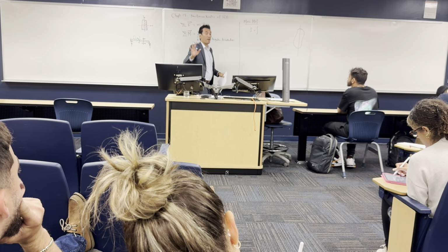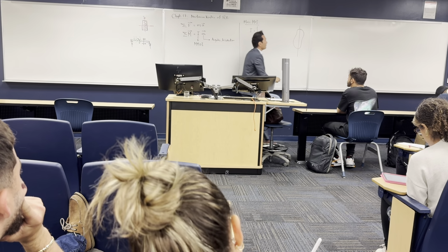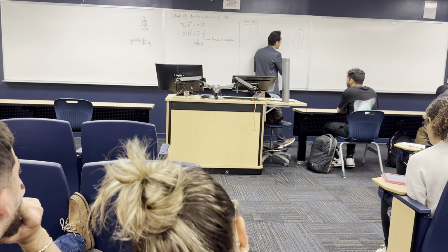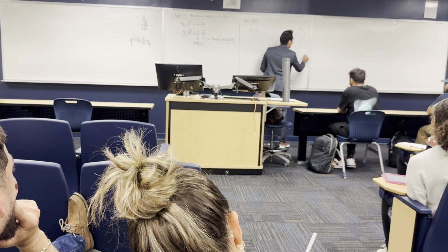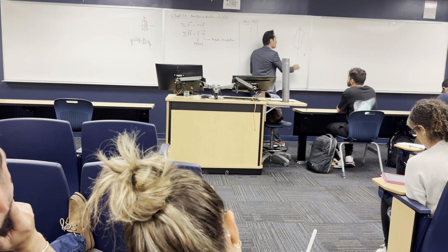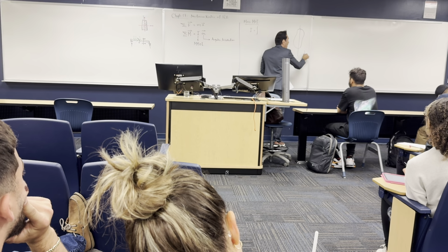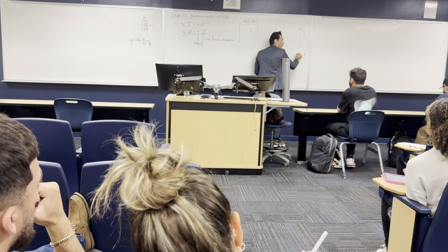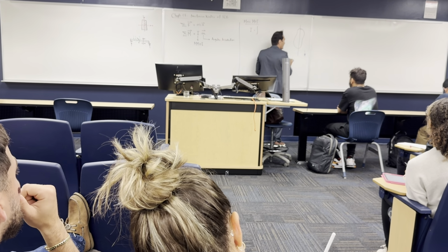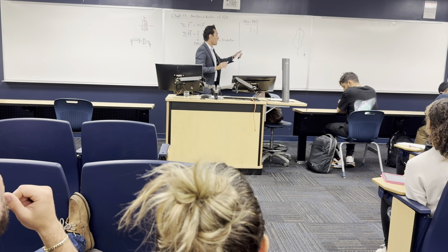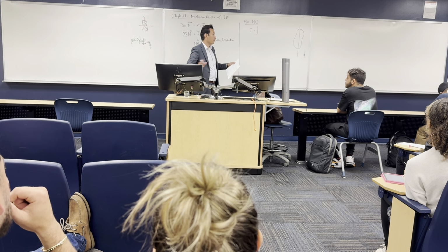To get the moment of inertia about any axis, like let's say this axis, and you have a mass here, first you need to get the mass moment of inertia about the CG of the mass, and then transfer this mass to be here. Okay? So that's what we call the parallel axis theorem. So this is the first thing.